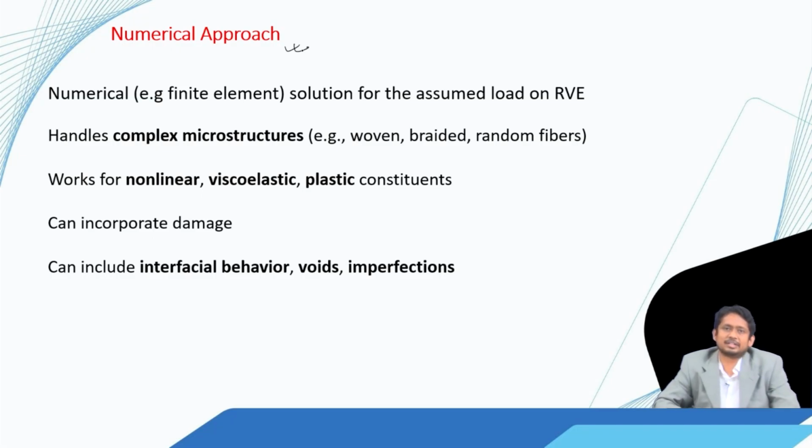So far in all the approaches, we assumed an RVE with given stress or strain, analyzed what is happening inside, and from that solution found the equivalent elastic modulus and other properties. But those solutions were mostly analytic or semi analytic.